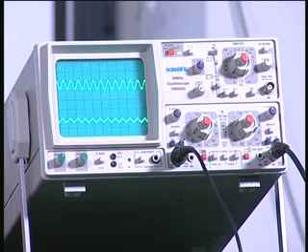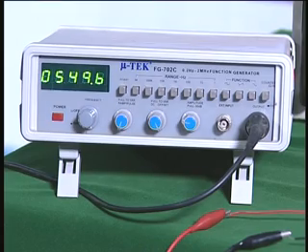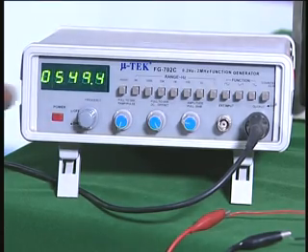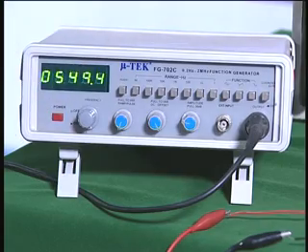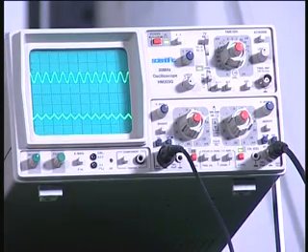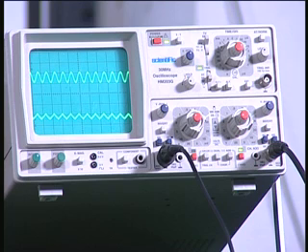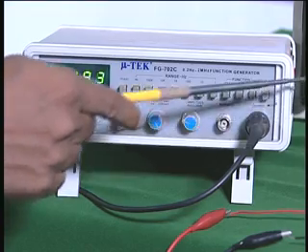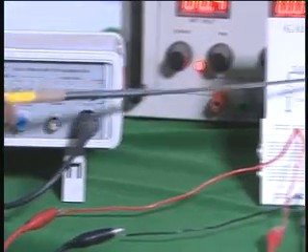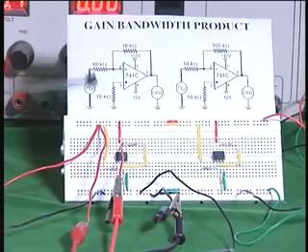But you can see the bottom signal is having lower amplitude than the top. This happens when I press and go into the 1 megahertz range, several hundreds of kilohertz away it starts decreasing, and we can precisely calculate from the amplitude when it becomes 0.7, and you would find it will be very close to 1 megahertz, because the gain bandwidth product for the 741 is very close to 10 power 6. So this corresponds to the gain of 1 in the circuit that I have shown. This is the circuit that I have now used with a gain of 1.